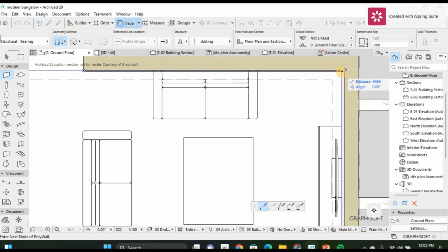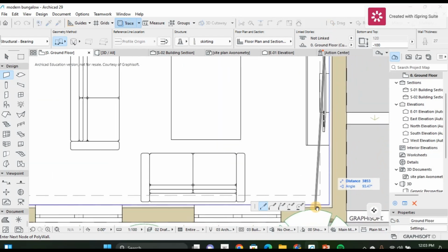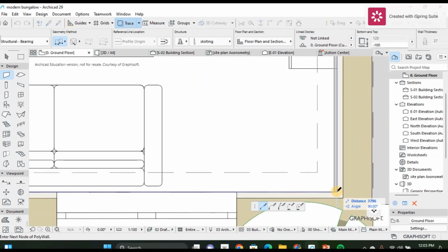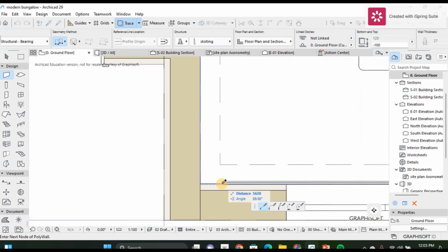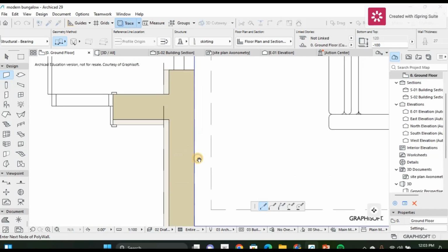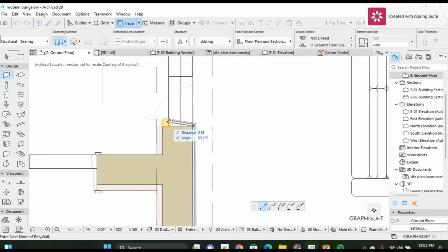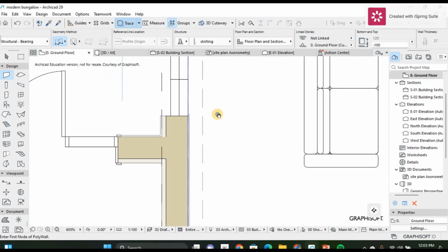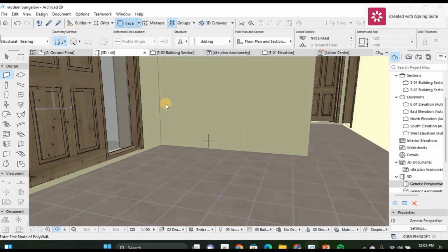So I'm going to come here, and we're just going to see what it does for our 3D. So I'm going to draw it like this, like that, until we reach the end. Where there's an opening, you don't put a skirt because it's not actually possible to have a skirt in an opening. So I can just continue. Let me just follow the whole thing up to where the door is, like there. And then I click.